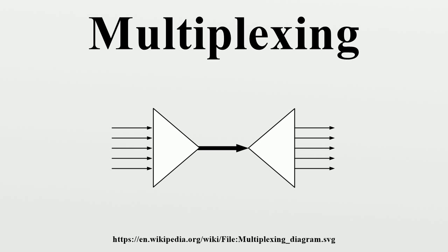Digital bit streams can be transferred over an analog channel by means of code division multiplexing techniques such as frequency hopping spread spectrum and direct sequence spread spectrum. In wireless communications, multiplexing can also be accomplished through alternating polarization on each adjacent channel and satellite, or through a phased multi-antenna array combined with a multiple input multiple output communications scheme.